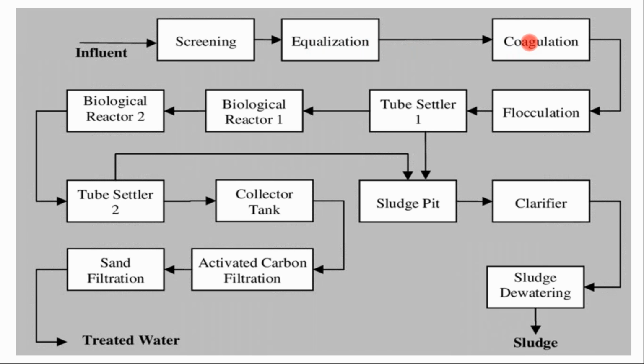Some particles, salts, or solids are dissolved in the influent, and that is why they are not settled by gravity itself in the equalization. They are now going to settle in the coagulation or flocculation unit. So, coagulant and floc. These are the words used in this process. If you use a coagulant for settling the solid particles in the process, that is called coagulation. The coagulant may be alum or alum derivatives, or different chemicals that are nowadays used as a coagulant for collecting. So what exactly is the process?